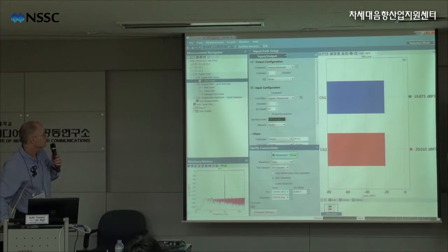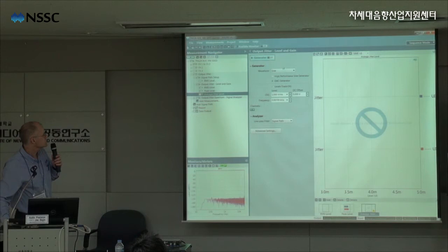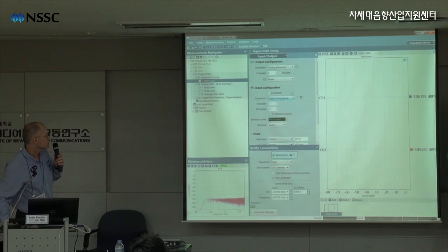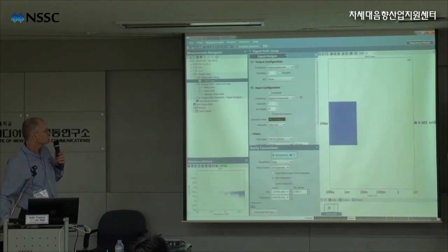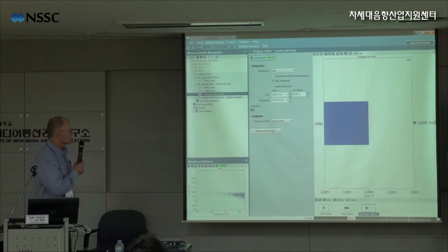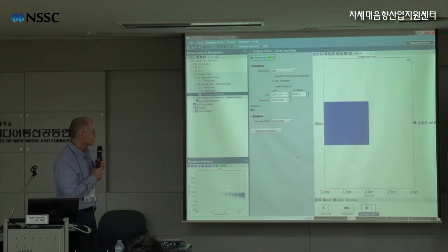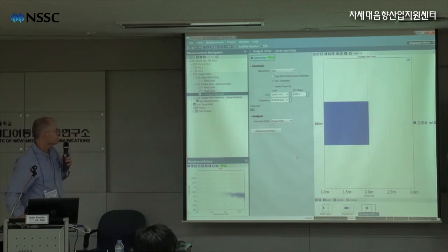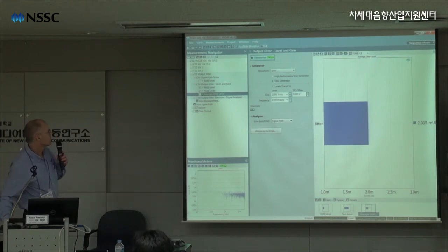And what this test does is, instead of looking at the audio, we can look at the jitter in terms of unit intervals or seconds. So essentially we're measuring the jitter level coming out of this analog to digital converter, while generating a signal at 1 volt RMS with a frequency of 997 hertz.